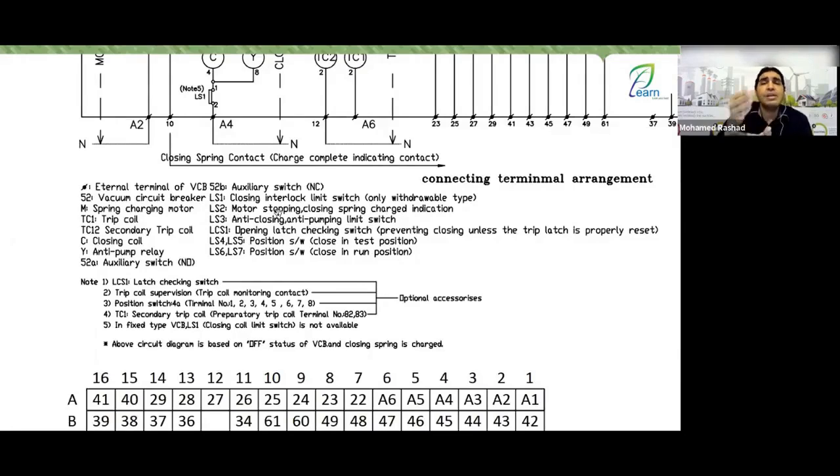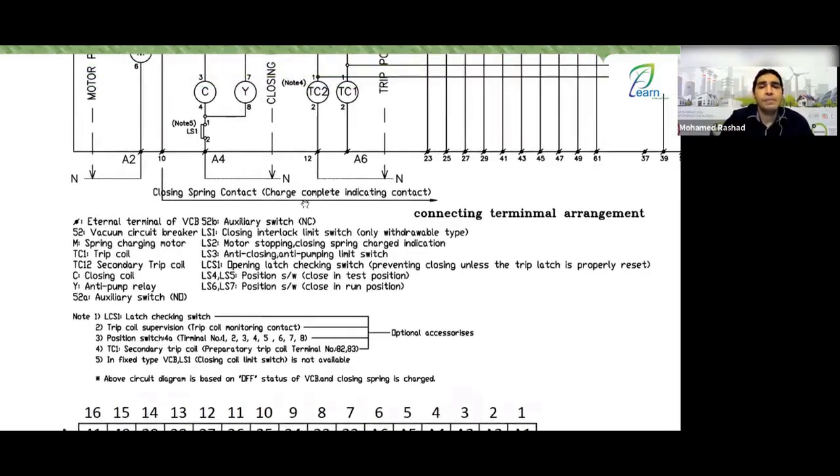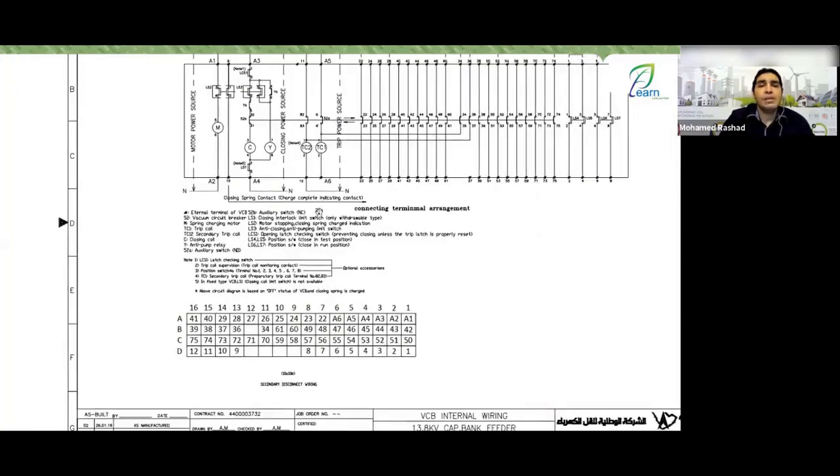Closing spring, a charging indication. Yes, it means the spring is charged. So what will it stop? The motor. This means that it should supply DC to the motor if the spring is not charged, and disconnect the DC from the motor if the spring is charged. All right, let's not forget. Very good. So we haven't forgotten anything.